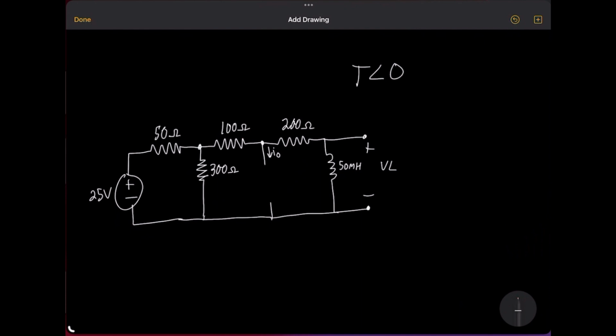So, since this circuit has sat for a very long time, we're going to replace this inductor with a short circuit. Since the current through everywhere should be equal, or constant at this point, a steady state, it shouldn't be changing over time anymore. Okay, so what we want to figure out is what is this current, we'll call it IL or something. What is the current through that inductor area where we had short-circuited it? Because we're going to use that value for later in this problem when that switch gets flipped back over to determine what is going to happen.